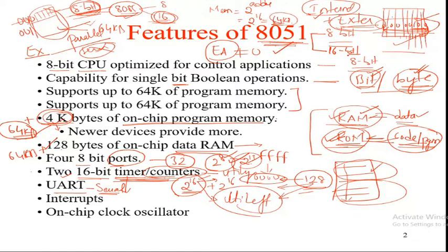But in the microcontroller, as you have bit and byte accessing, both the parallel data transferring scheme and the serial data transferring scheme are there. That can be implemented with the help of an additional peripheral, available internally in the microcontroller, that is the UART, for the implementation of serial communication. So directly we can handle serial communication with the 8051 microcontroller.